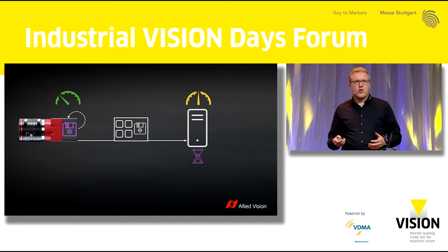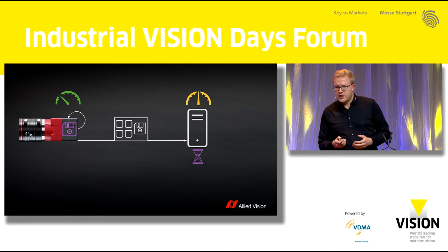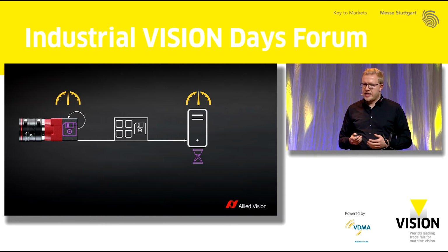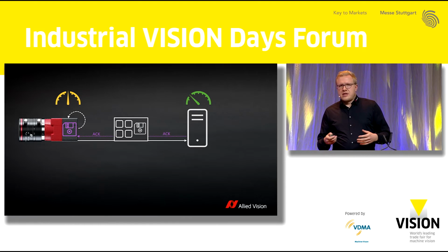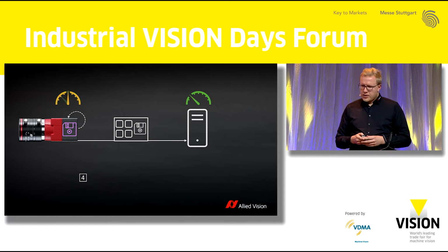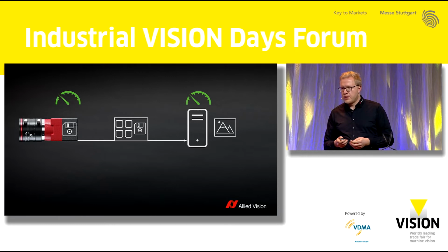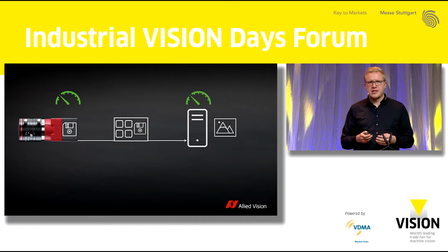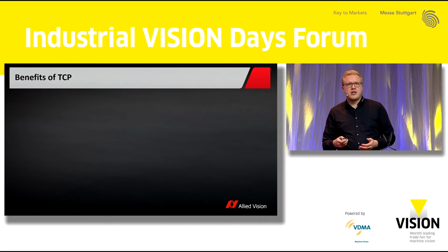What happens now is that the camera buffers the incoming image data from the sensor in its internal buffers. And it does so until the host system sends the next acknowledgement, which then means it sends out the additional data in the scope of the window size that had been agreed between the host system and the camera. So that really means there is not really a risk of having lost images in the system as long as the camera has enough buffer to catch up these temporary events.